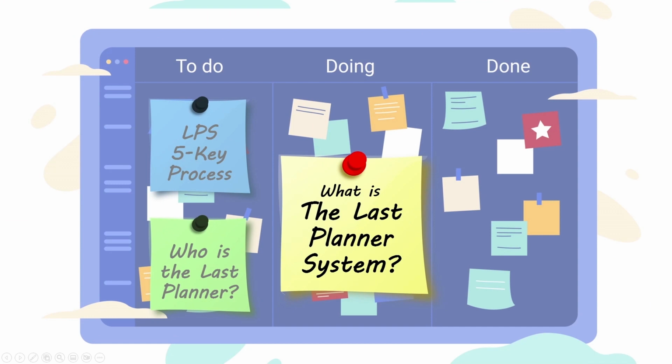The Last Planner System is a method of project production that encourages the development of a dependable workflow between multiple stakeholders. Potential obstacles can be identified and removed by the LPS before they can cause any flow slacking. The Last Planner System focuses on creating and sustaining flow in work processes by encouraging talks between construction team members so they might see concerns before these issues disrupt workflow. Pull planning is used to achieve this.